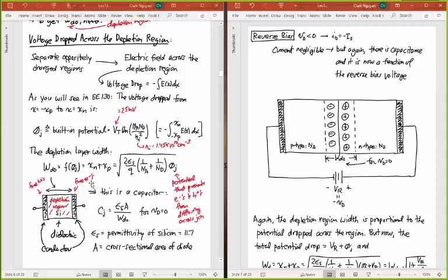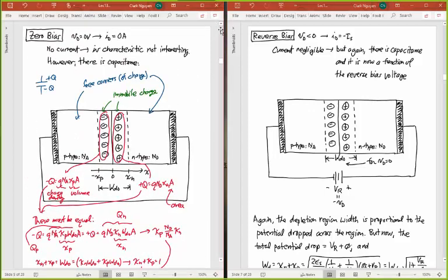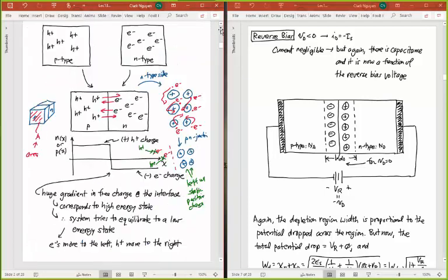And so I talked about putting more voltage across this. Let's do that now. Okay, that's what's called reverse bias. So I've left you with, at 0 volt across this, this looks like a capacitor. But as I apply more negative voltage across this, so negative voltage means I'm putting the negative part of the voltage on the P side, the positive part on the N side. So if this were a diode, then actually what the diode would look like, and maybe I should have done this a little earlier, which is you know, where the diode symbol should be.